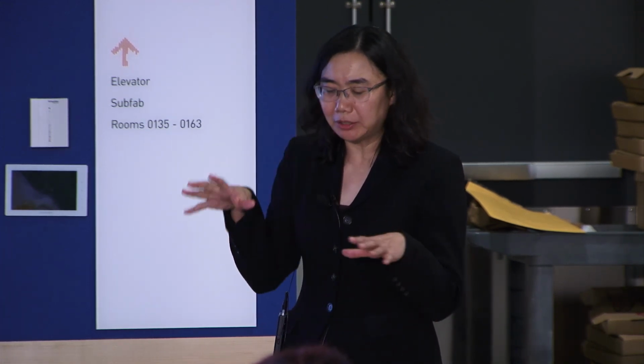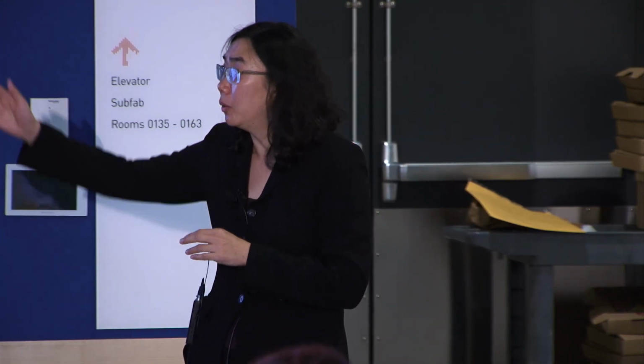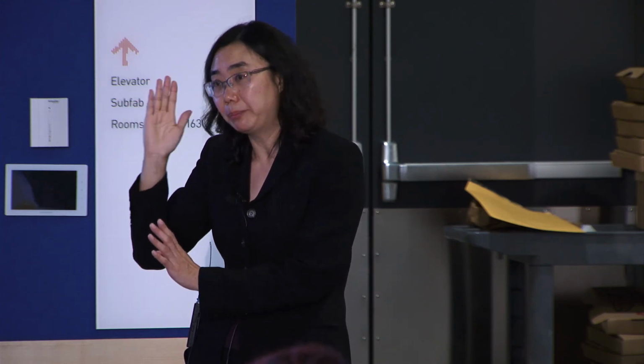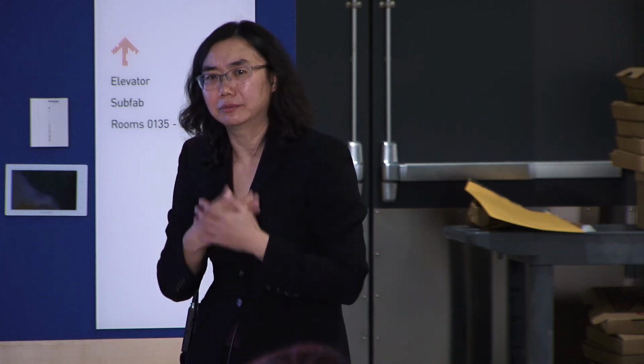From a practical point of view, I think one of the big differences, for the people in the audience who are not familiar with the field: what I showed for the spin torque MRAM, one of the advantages is the structure is very simple. It's a two-terminal device. You have MTJ and you have transistor. That's all. The structure is simple, so that means you can pack them very densely. The spin-orbit torque is a three-terminal device.